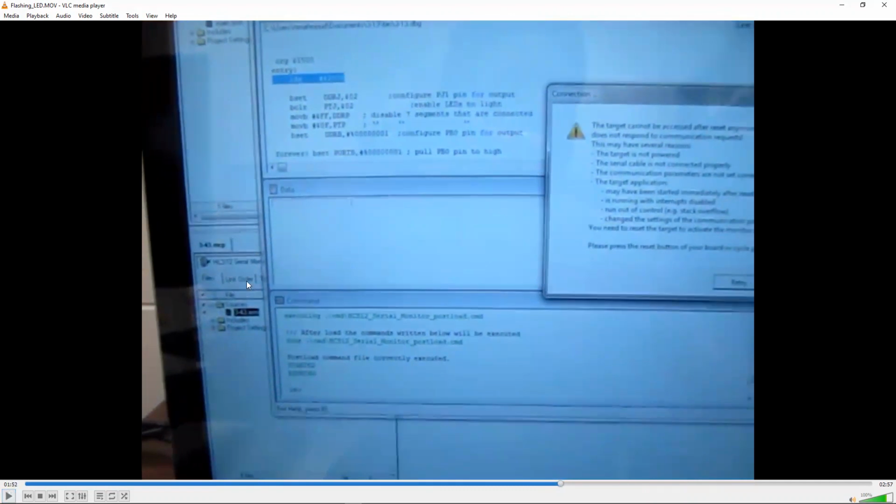Okay, now let me think. Look here, I want to tell you something important, guys. Again, I told you, you can control the time easily. Just change this number in your program, very easy, right? So my question now: if I make this time very tiny, very little time, what do you think is going to happen? If I make it 1 microsecond or 1 millisecond, for example, can you see the flashing? Can our eyes see the flashing, 1 millisecond on, 1 millisecond off?